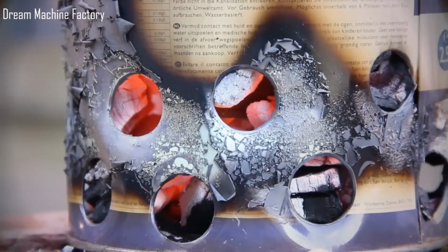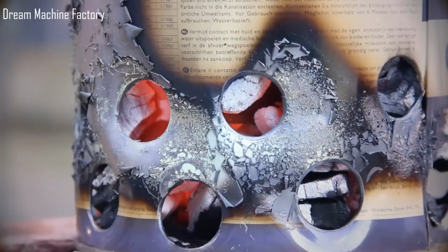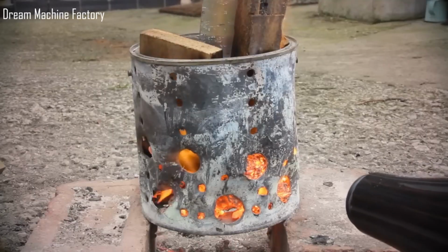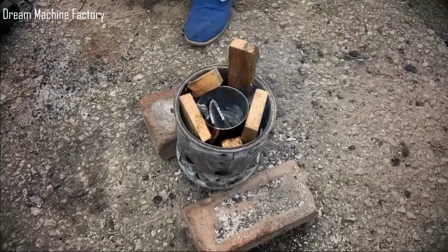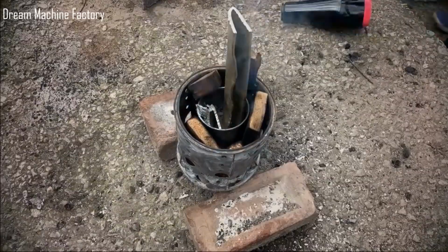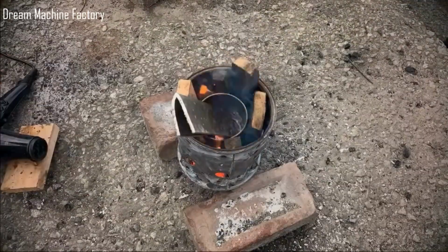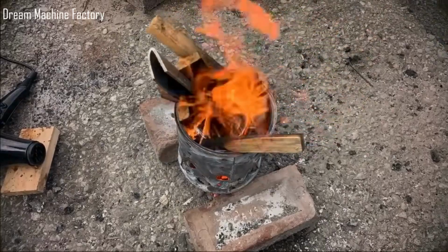Once the fire is burning steadily, allow the furnace and crucible to heat up so any paint or coatings burn away. This step should be done at a safe distance to avoid inhaling fumes. When the flames are established, place the crucible into the furnace and surround it with additional fuel, maintaining at least a 35 mm gap for airflow.